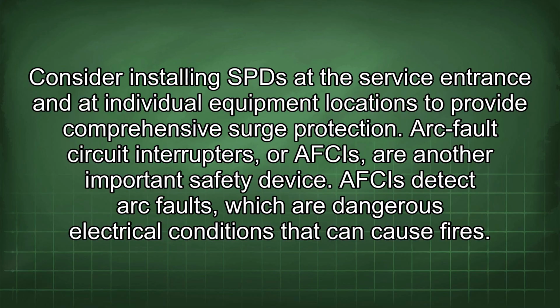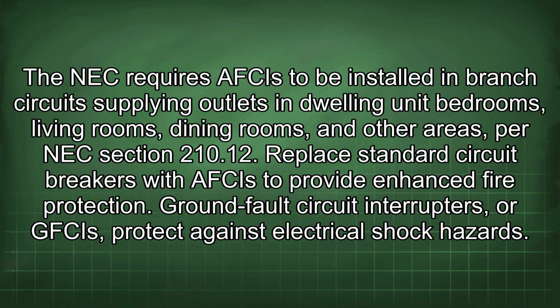Arc fault circuit interrupters, or AFCIs, are another important safety device. AFCIs detect arc faults, which are dangerous electrical conditions that can cause fires. The NEC requires AFCIs to be installed in branch circuits supplying outlets in dwelling unit bedrooms, living rooms, dining rooms, and other areas per NEC section 210.12. Replace standard circuit breakers with AFCIs to provide enhanced fire protection.